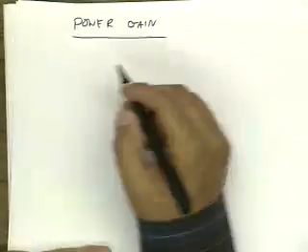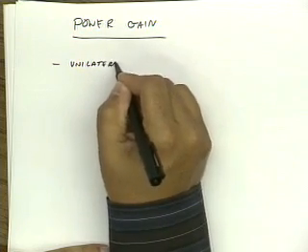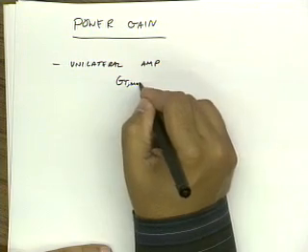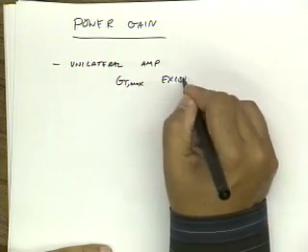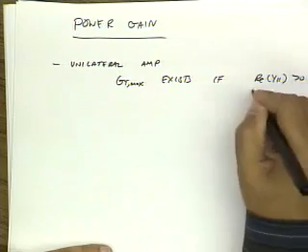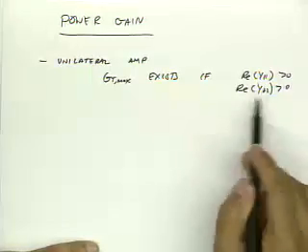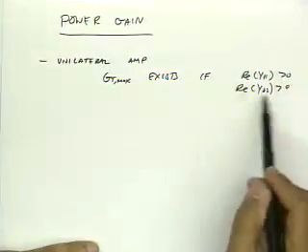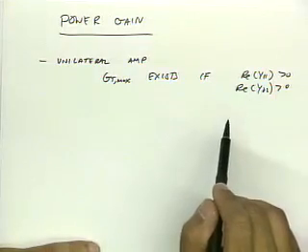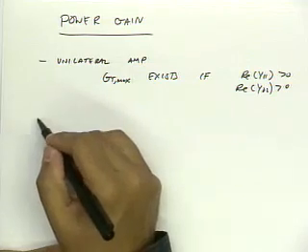So what we found is that for a unilateral case, GTmax exists if simply real part of y11 is bigger than 0 and real part of y22 is greater than 0. And if it's a physical transistor model, usually this is true. So you almost don't need to check this condition, but usually it's already satisfied. So for a unilateral amplifier, we can always find the maximum gain.